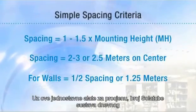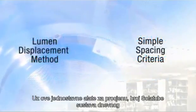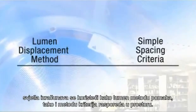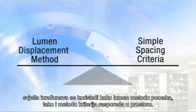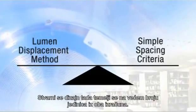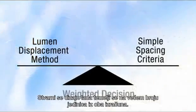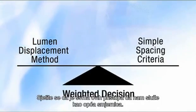With these easy estimating tools, the number of Solatube daylighting systems is calculated using both the lumen displacement method and the spacing criteria methods. The actual design is then based upon the higher number of units from both calculations. Remember, this approach is intended to serve as a general guideline.